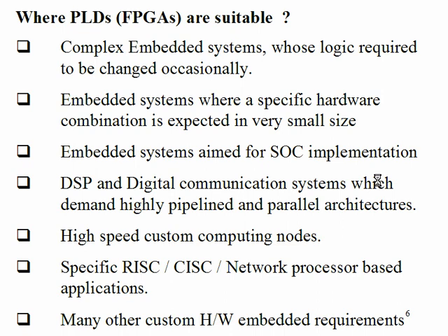You got the point? Multipliers can be realized through multiplexers and lookup tables like what we said yesterday. But rather than that, they put the multiplier logic directly in, which obviously runs at very high speed. Configuring multiplier lookup tables and muxes will take more time for multiplication. But if the multiplier is implemented completely at the silicon level in an FPGA, it obviously works faster.